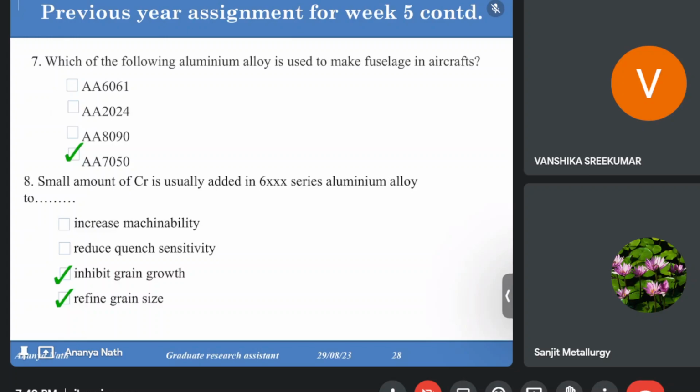We may use the T6 condition for the optomechanical components because it needs to sustain very high frequency movement and a very rough condition with great rigidity. For the same alloy, when I use it for making the aircraft body, we can use the T7 condition, because T7 is overaged, so that has some ductility along with a lot of hardness. So it's possible. These alloys are used at different heat treatment conditions for different applications in the same product.